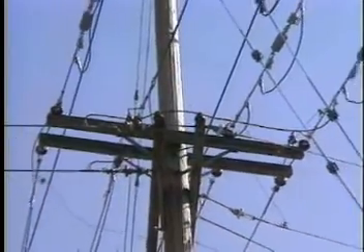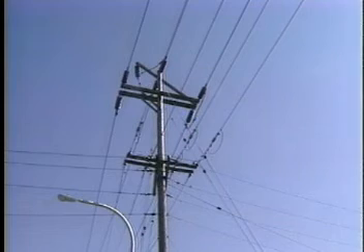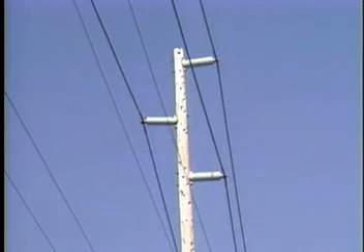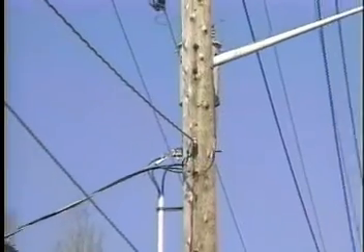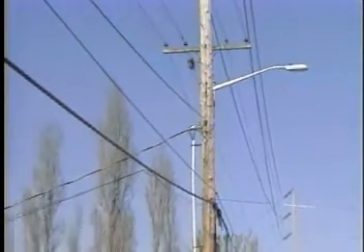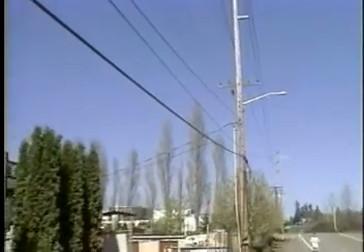Aerial placement of fiber optic cable may be an attractive alternative to underground placement, especially when existing right-of-ways and aerial structures are already in place. Although the EMI immunity of fiber optic cable allows its placement almost anywhere on a utility pole, it is usually placed in the communications or free space below the phase conductors of power lines. In many cases, a metal messenger must be installed first, with the fiber optic cable or duct lashed to the messenger. Alternatives to metal messengers include figure 8, ADSS or OPGW cable types.